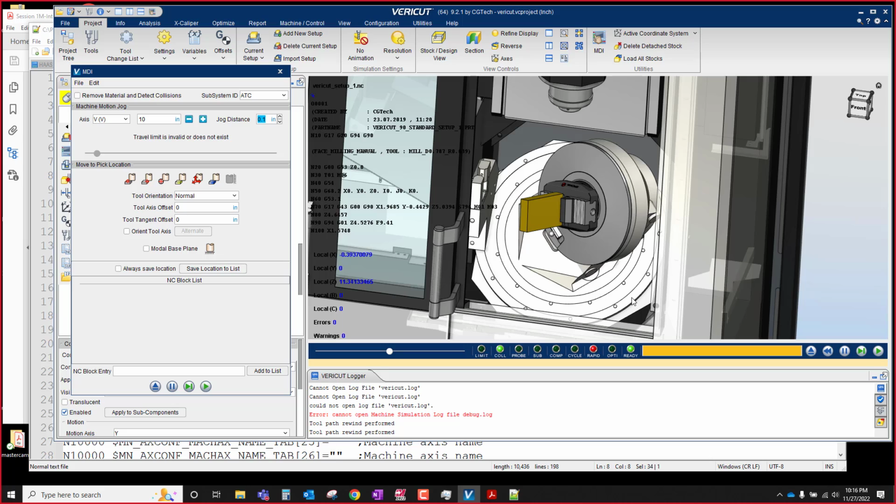Once that process was done, the robot loader would take it and load it in the pallet station for the machine. I think it had like 80 pallets. That way, at the end of the shift, at the end of the day, the guy could have, you know, 80 parts or 60 parts waiting to go. The whole process of actually machining the blade took roughly 15, 20 minutes. The scanning, building the stock model, the toolpaths in NX, the verification itself, and then the go, no go took about 8 minutes.